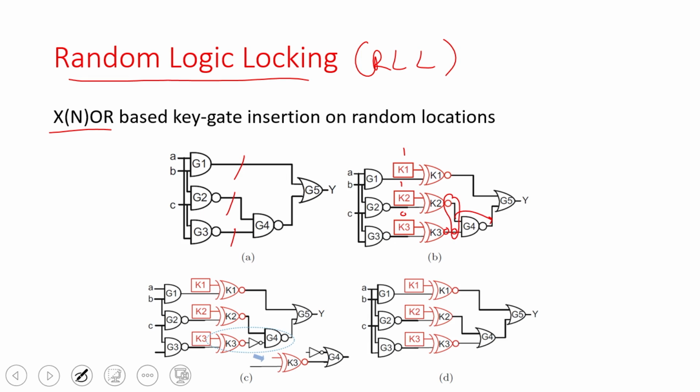So, this is what is basically discussed here. I put one NOT gate here and one NOT gate here. So, this XOR becomes XNOR and there is one more NOT gate, and then I will pick this and this, I move here. So, I will get this design, right. So, this XNOR NAND becomes an OR gate, right. This is the simple logic.